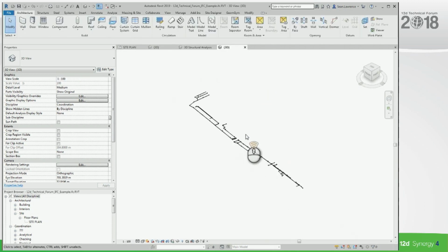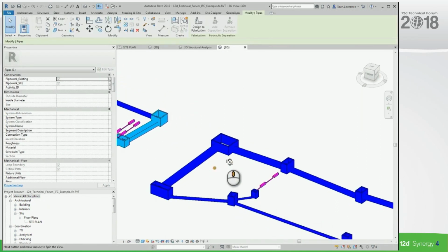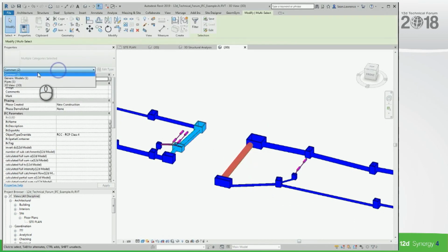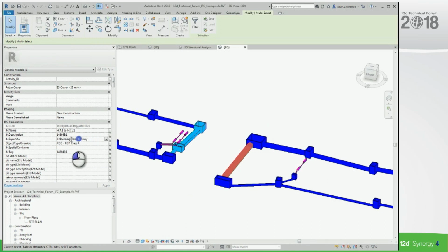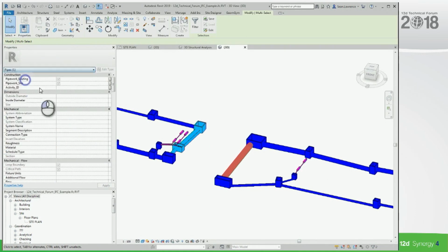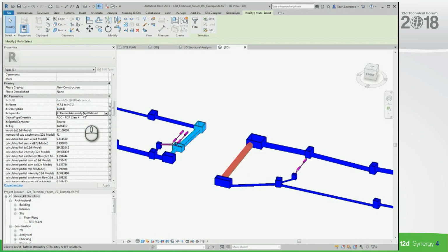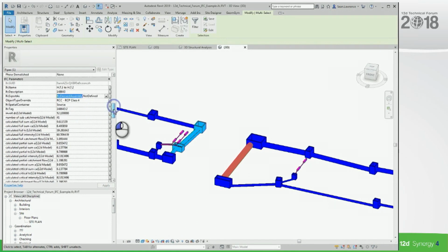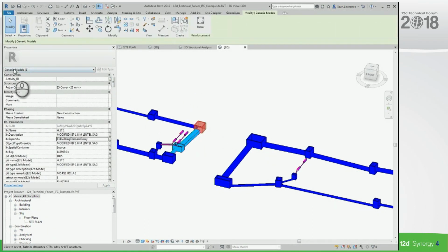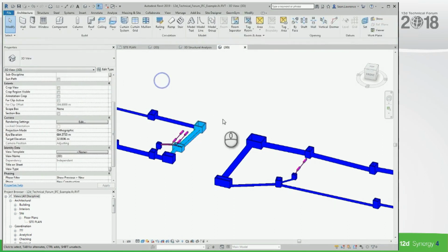Interrogating this model allows us to see all different kinds of data that are coming through from the 12D attributes into Revit. If I highlight over this pipe here, you'll see that there's actually 2 pipes per pipe segment inside Revit. One is a building element proxy, which has no data inside it, nothing for us to use. And the other one that's come through is a pipe, which is a building element assembly, which is what I mapped it to prior to in the import options. But you see all the juicy data that we get on that left-hand side. It's got everything. So mapping your attributes and checking that your calculations are right is essential for when we're trying to interrogate something in Revit.